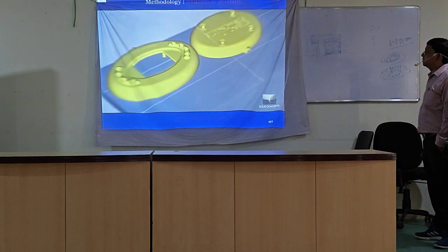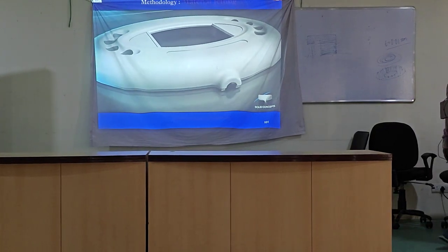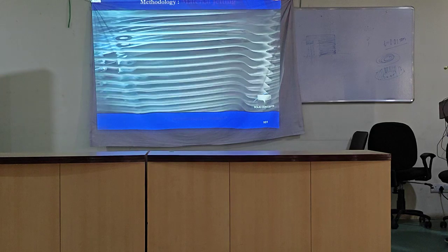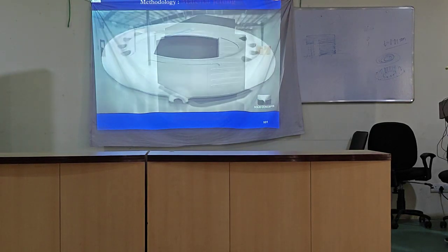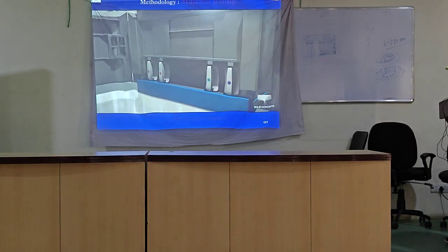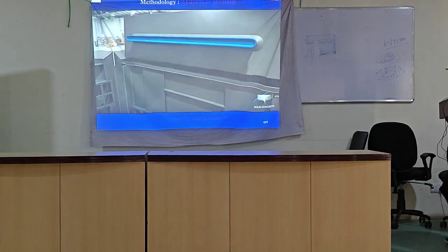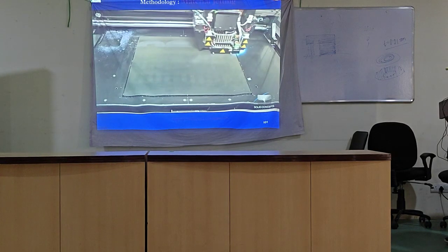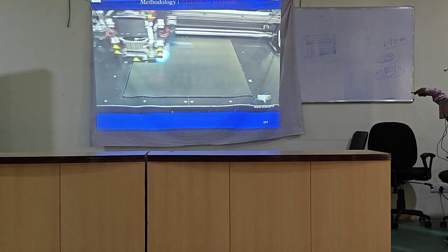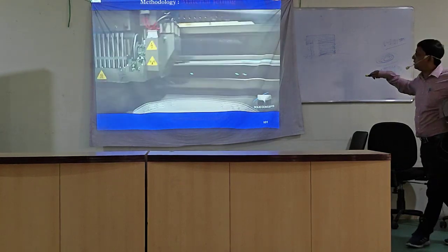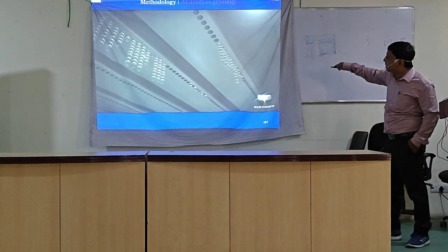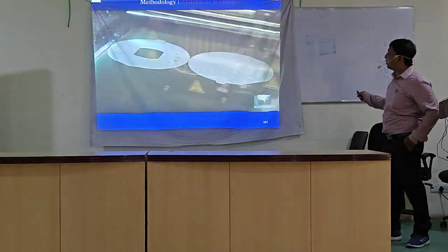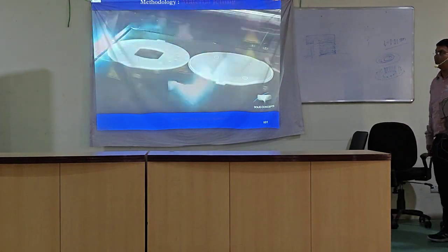The PolyJet process begins by slicing CAD data into cross-sections or layers, as thin as 16 microns. The slicing gives the cross-sectional information. Data is then transferred to the PolyJet machine, which begins constructing the object one layer at a time. Now see, this is depositing the material followed by UV cure. Depositing material through this tiny nozzle, selectively, followed by the UV curing.